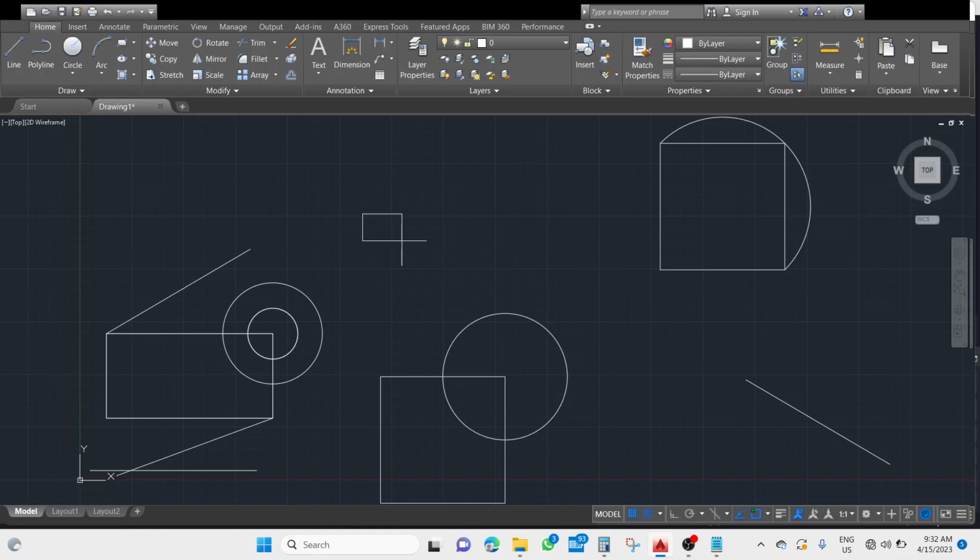Now I have only the dimensions, I don't know the other corner point. At that time, it says specify other corner point or area, dimensions, rotation. So I can give the area, I can use dimensions, and I can use rotation also. Here I have to give the dimensions. In the word Dimensions, the D alphabet is in blue color, so I simply press D and enter.